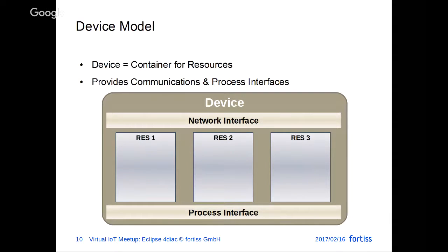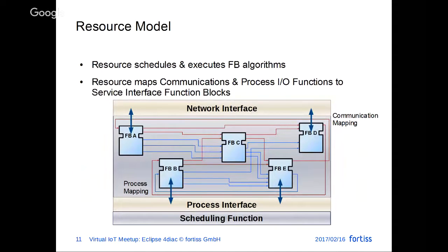In devices, we have so-called resources. Resources are a grouping. This is especially interesting when you are developing bigger applications, because resources are shielding their execution from each other. If you look inside a resource, what you can see here is that the resources are finally the elements which will execute the function blocks. So the resources are in charge of delivering input events and transporting output data to the according inputs.